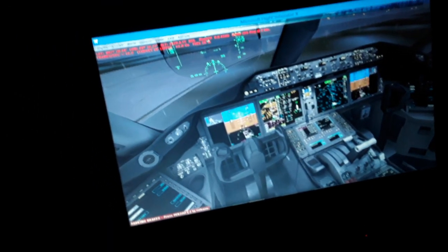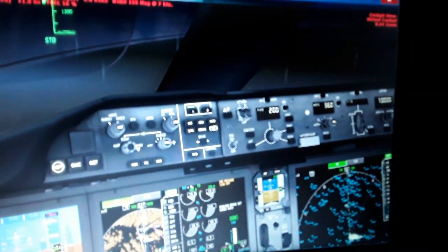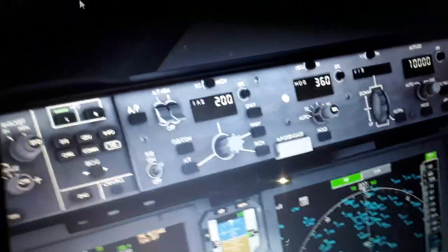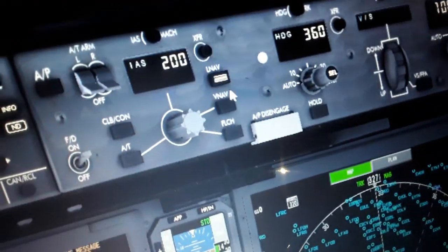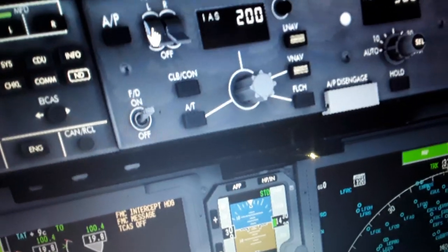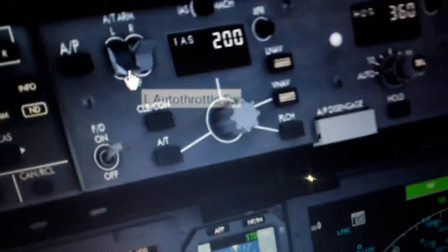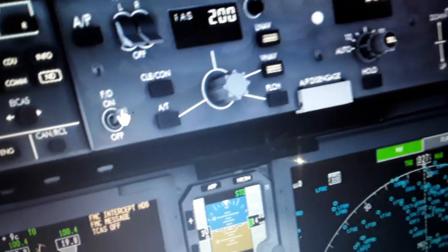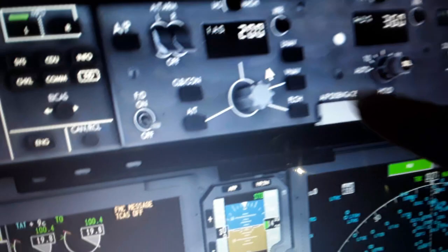So now we need here, over here, autopilot flight director system panel. We need to fix a few values. So you see the autopilot flight director system panel over here, the auto throttle left and auto throttle right, autopilot engage and disengage switch, LNAV, VNAV over here, auto throttle arm and disarm. Flight director cancels over here the modes.